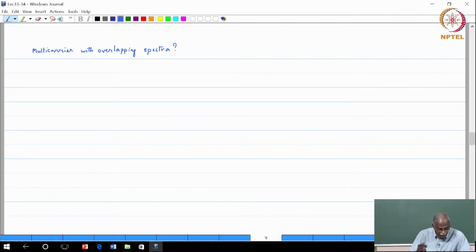However, if you think about what we said about the DFT or the IDFT, what were these? The DFT was as if you were passing the signal through a set of filters, which was this type, right, the rectangular window response.